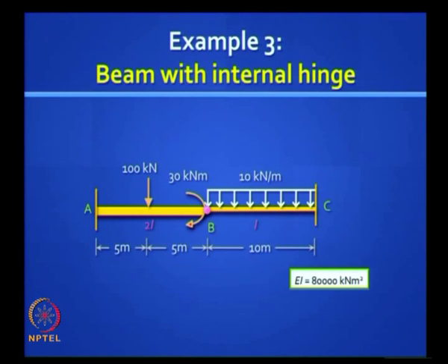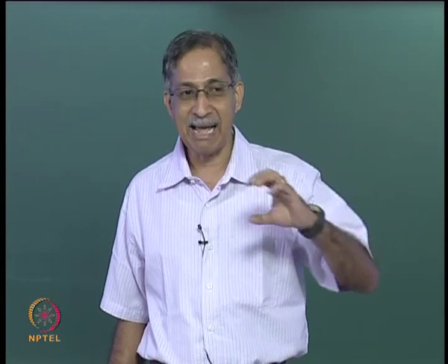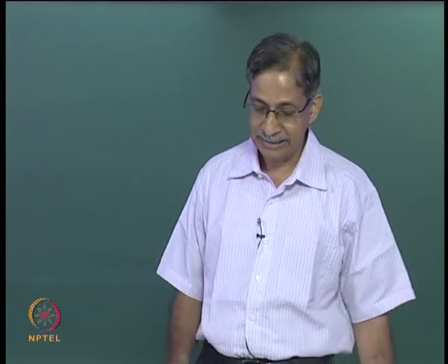How to deal with an internal hinge in the reduced element stiffness formulation. You will find that it is easier to do this here than in the conventional stiffness method, because there you have to artificially create a clamp and all that. Here life is easy, this is all you need to do.